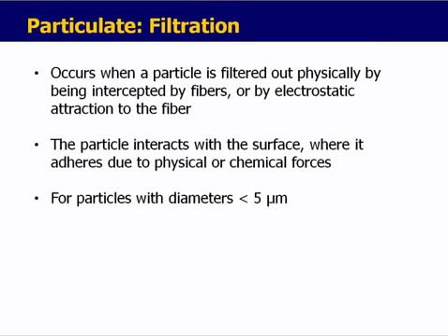The third system is filtration. This is extremely common in household and office place settings. A particle is filtered out physically by being intercepted by fibers or by the electrostatic attraction to the fiber. The particle interacts with the surface where it adheres due to physical or chemical forces. It is commonly used for smaller diameter particles, less than 5 microns.